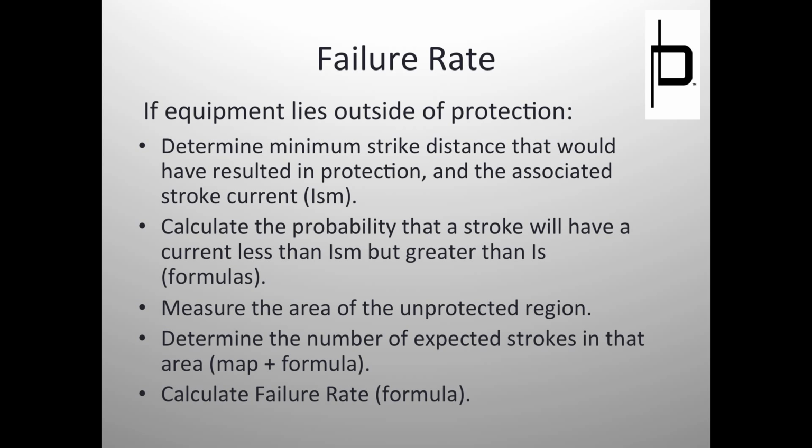Right. Now, the smallest stroke current that causes flashover. Is that the actual stroke current of a random given lightning strike? Probably not. We don't know what it's going to be. The actual stroke current may be greater, may be smaller, and the BIL will absorb it. We've just defined our sphere based on the worst case.